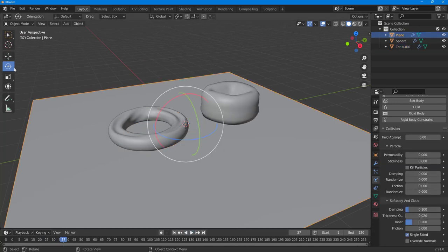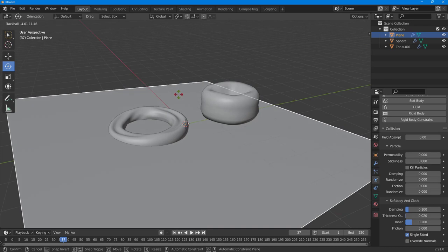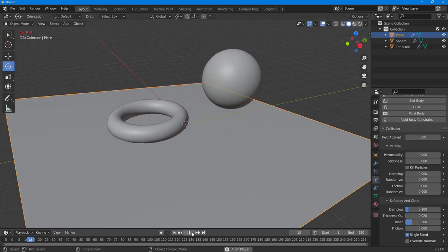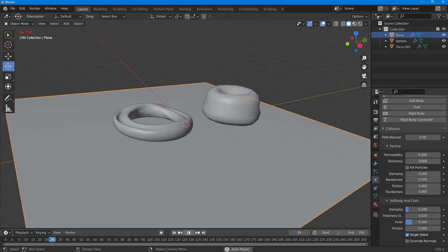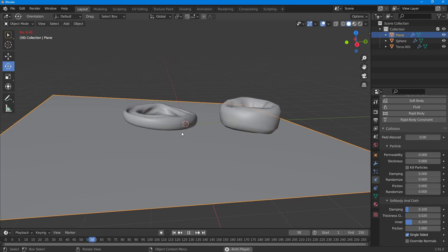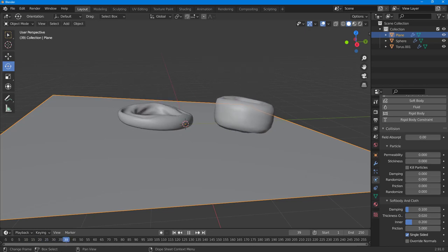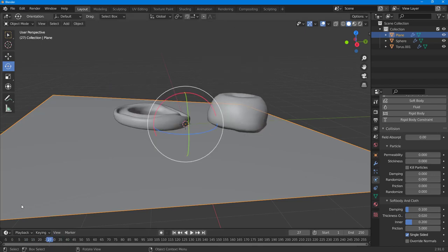We can also rotate this a bit right here, just like this, so that it generates how it actually feels. So you can see that it now slides over as well, because this is slanted right here. So you can see that the physics and the collision actually take place just like this. And it seems as if these things are very, very soft, and it is colliding with that hard object right there. And that is how you can work with soft bodies inside of Blender.